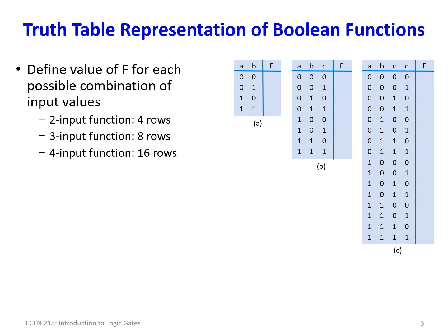And what I do, if you're going to create one, is I always put things in order, A, B, C, for instance, or A, B, C, D, and then you just start counting up in binary. The way to note this is that this one is constantly oscillating between 0 and 1, and this one is every other one, and so on and so forth. You notice this is now a group of 4 zeros with another group of 4 ones.